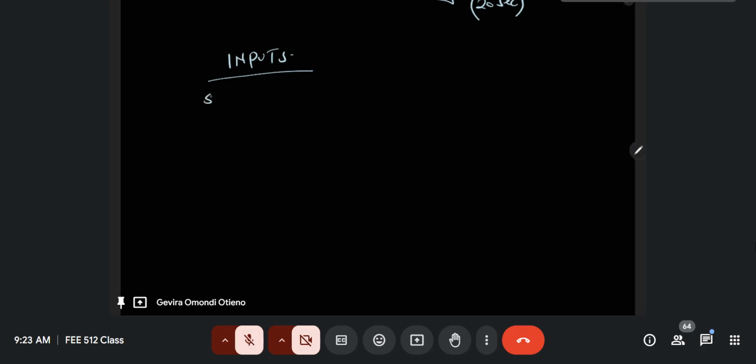Now, of course, the same culprits: we expect a start push button, and the start push button is already its condition. So the PLC wiring for this, so that you also don't get confused: the PLC wiring for the start push button is normally open.